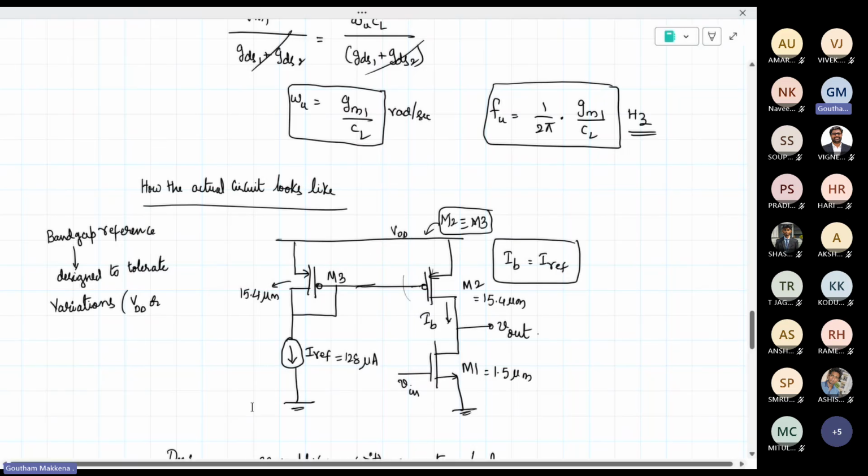So this is the most basic current mirror, but the PMOS type. We discussed the NMOS type. It is exactly the opposite. So all the NMOS transistors will be stacked from ground to up. Of course, the PMOS will be stacked from VDD towards the ground. Okay, so this is the basic PMOS current mirror. So whatever is the IREF here, the same IREF flows through this one as well.